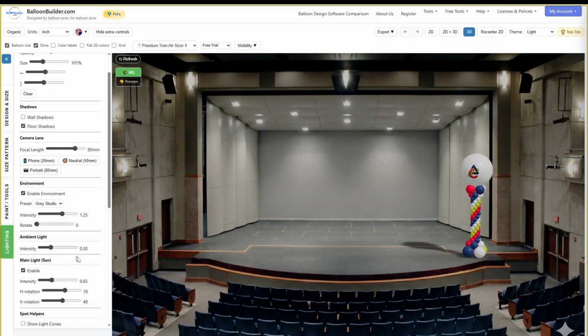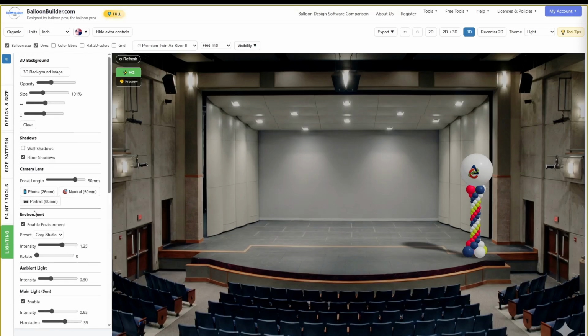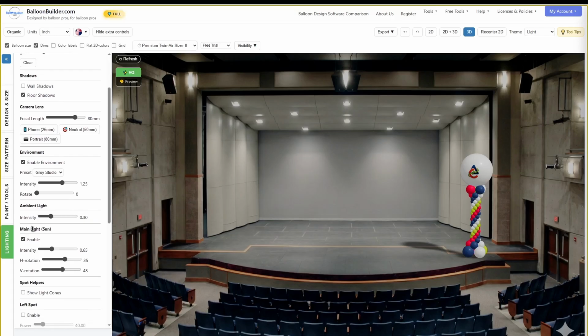And then if you want to adjust the direction of the light, colors of the light, everything, it's all adjustable over here. For example, the sunlight is now the main light, so we can increase the intensity of sunlight. Now the intensity of the sun is much higher, so it's brighter.